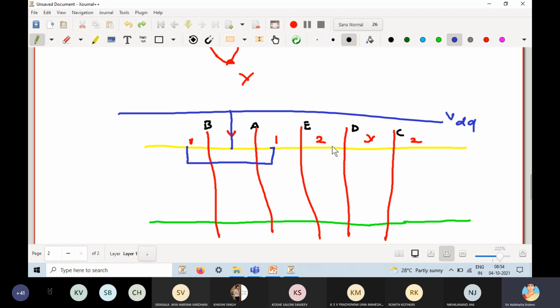You can understand why I have joined like this. Don't think that it is an arrow, okay? It is a V. So whenever metal joins with P diffusion, I have a contact cut, either a dot or cross. It doesn't matter.